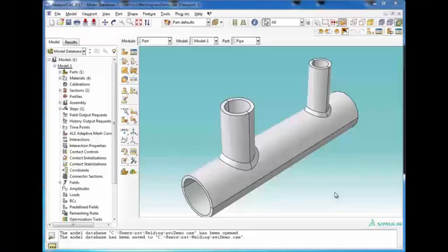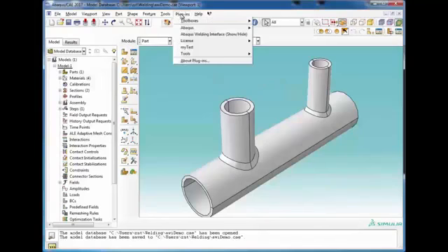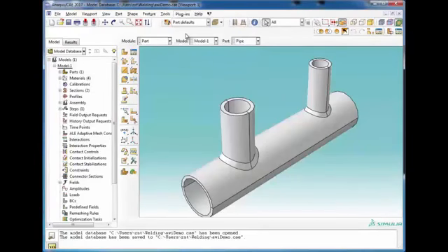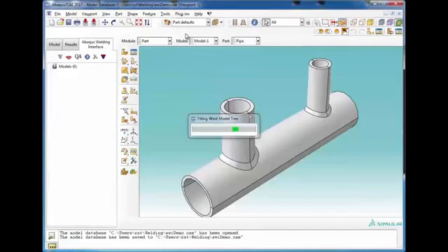Welcome to a demo of the Abaqus Welding Interface. The AWI, as we call it, is a plugin that was developed for Abaqus CAE that specializes in setting up weld models. When we bring it up, we see there's a tree here. We have options like bead color coding, highlighting, and some QA tests. These are useful if you're new to the plugin. You can run some of the example problems and get a feel for how things are set up. There's a user's manual, an option for installing workshops, and then the post-processing.